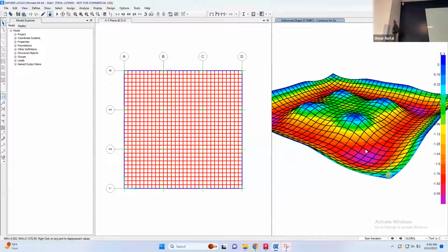So if you have a very long corridor, like this corridor, the slab on this corridor is supported by a beam here and a beam here. And it's a very, very long slab. This slab acts like a one-way, only bending this way. It's not easy to bend this way because it's very long. It's supported from here and here, so it only has one-way bending moment. So usually the main reinforcement for the one-way slab is in this direction, okay?